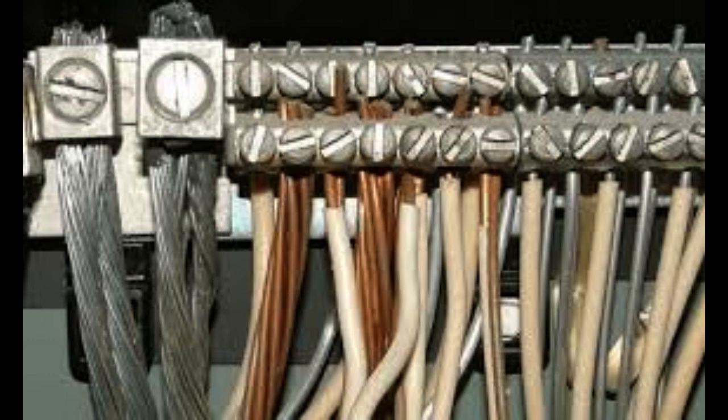5. Bonding and grounding; 6. Conductors; and 7. The operation of installed ground fault or arc fault circuit interrupter devices. And H. The absence of: 1. Trip ties on 250-volt overcurrent devices or multi-wire branch circuits; 2. Appropriate connections; 3. Antioxidants on aluminum conductor terminations; and for main disconnecting means.